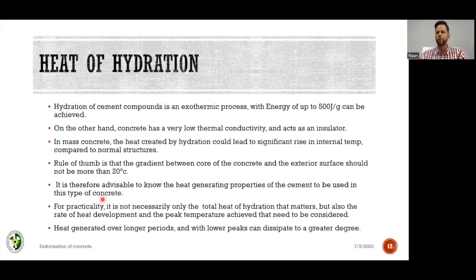The rule of thumb is you need 4 times the maximum aggregate diameter for your cube mold. So that's why we use 100 millimeter cube molds for anything using a 20 millimeter aggregate. You could go to a 26 millimeter aggregate, but you would be breaking the rules. It's better to then go for a 150 millimeter concrete test cube if you are using 26 mil aggregates or larger. You could go a little bit larger, up to your 36 millimeters, and then you have to use a larger cube, or you would need to scalp the cubes,